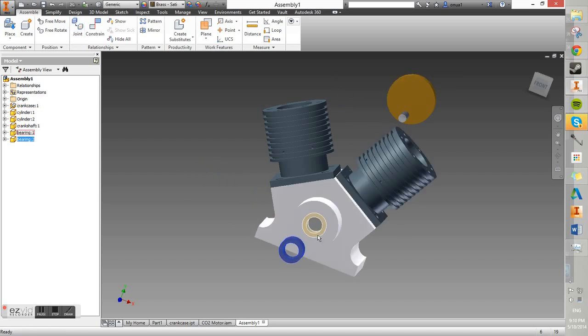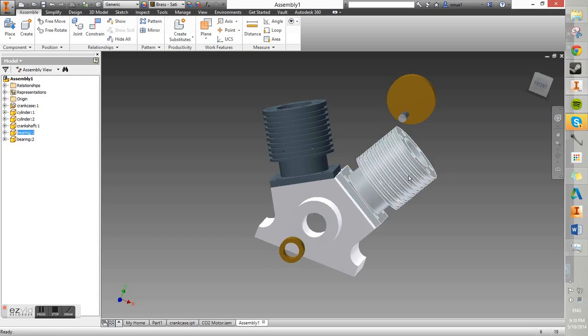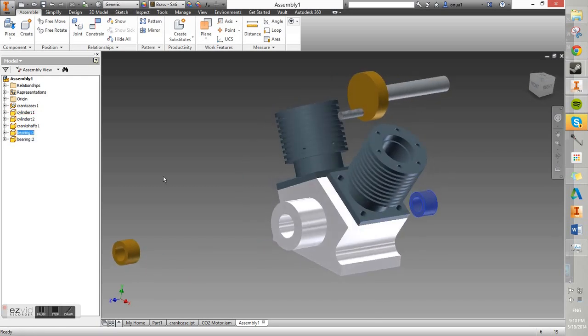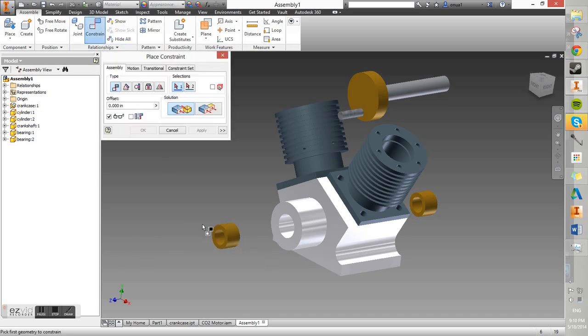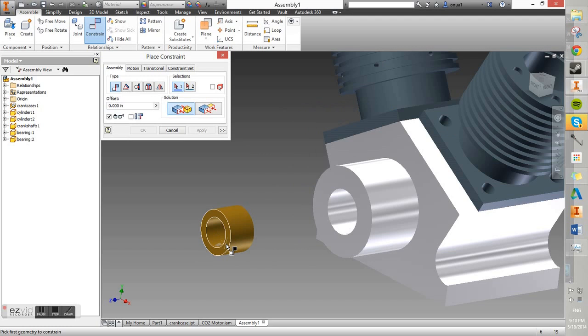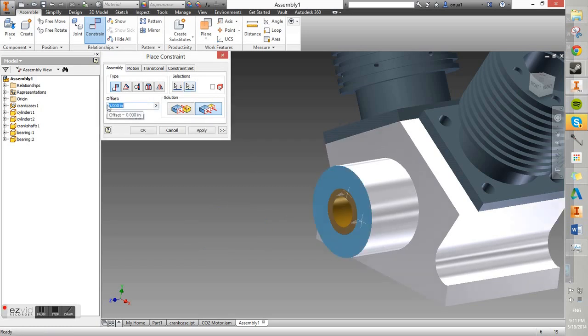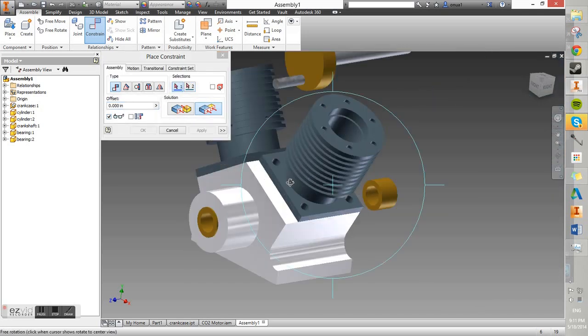So now if you notice that those are movable since they're cylindrical. They can move in both of their allotted ranges of motion. But those aren't in place yet, so let's constrain them into place. So what we're going to have to do is flush the edges. So we're going to want to flush that front edge together, but make it slightly offset by 0.1 out of the piece. If you notice, I went in, so we're just going to make it negative direction to make it pop out. Hit apply, so that way we can add more constraints.